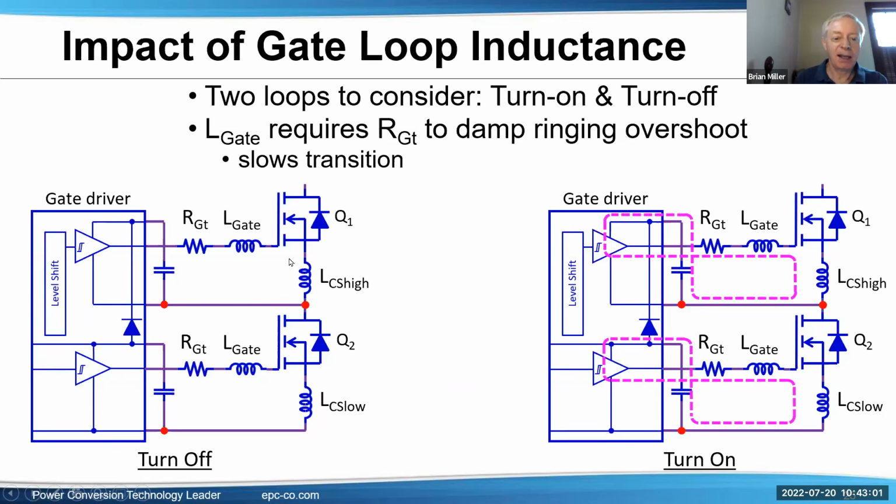On the top one, you would have the source, which is the switch node, which to some people seems kind of odd because that could be a noisy reference, but that is the reference for the top gate driver. So having something like the resistor on the top going to the gate, and then having the inner layer with its reference, the switch node, coming back to the driver. Yes, that'll help with overall performance and also noise too. So yeah, good point, good question.